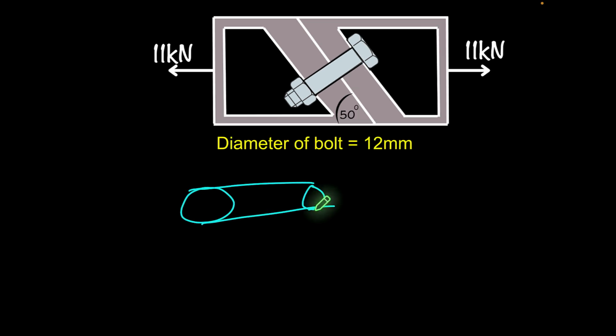So as a quick recap, if this diagram in blue represents our bolt, then what we're looking for if we're analyzing its tensile stress is the force would be acting perpendicular to our surface area right there. So that shaded region, that's representing our area in question, and our force would be pulling in either direction, equal and opposite force, just as you see up top. And that force will cause the bolt or the system to stretch in either direction. Hence, we have a tensile load there.